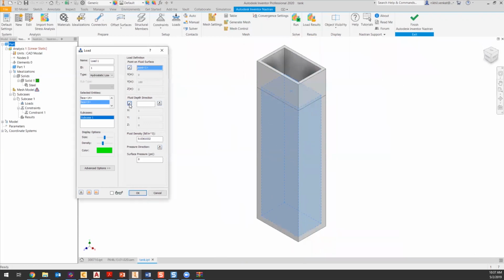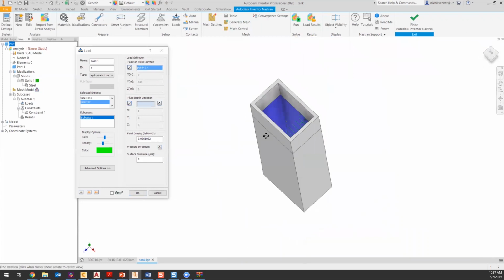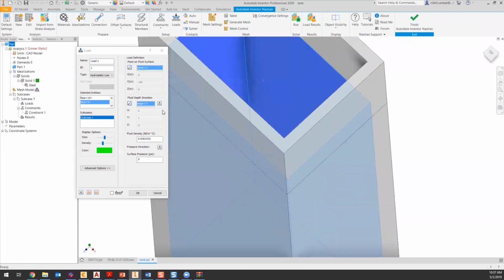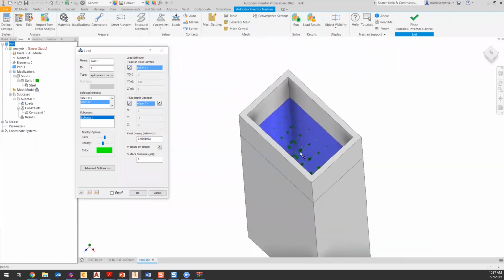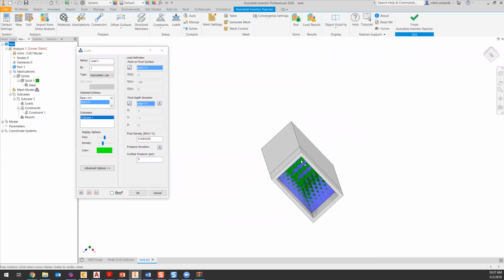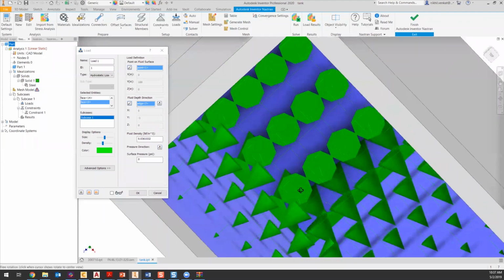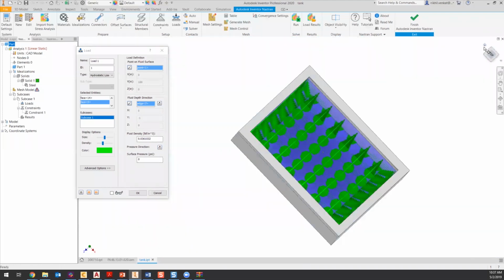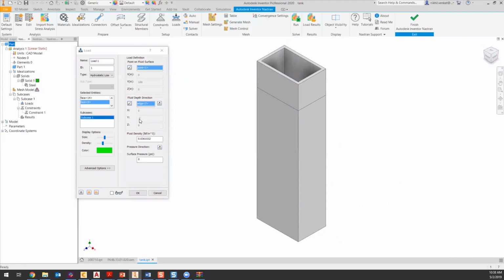You also need to select the fluid depth direction. So is it going upwards or is it going downwards, right? So that's the fluid depth. You can always change the direction of this. At the moment it's going to be downwards, which is what we want. Right, so it's negative y, as you can see here.